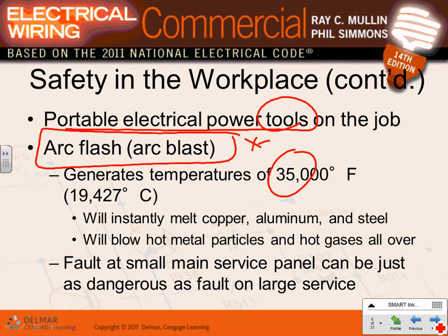So what's the rule? Since you're not electricians, your rule is 10 feet away. If any piece of equipment is being worked on energized, Zach, in the field, you have to move 10 feet away from that piece of equipment. Can I have a thumbs up, Chad? We got that one? To save yourself. You guys are not going to be working on that. Also, small faults can cause a lot of arc flash. If you're working on it and you're sitting right there, an arc right in front of your face, and you don't have the proper shield, you could lose your vision. Any comments? Can I get you to be scared of arc flash, arc blast? If I get you to be at least scared of that one, I did my job.